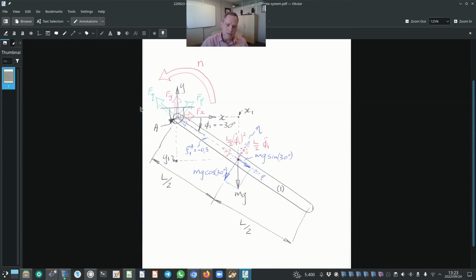and that makes sense because this mechanism is a single body rotating around a pivot point, and we can clearly understand the physics that as you pull the pendulum rod up, as you lift it, you will need more torque, and as the pendulum rod is falling on the other side, you actually need to reverse the torque and reduce the acceleration.